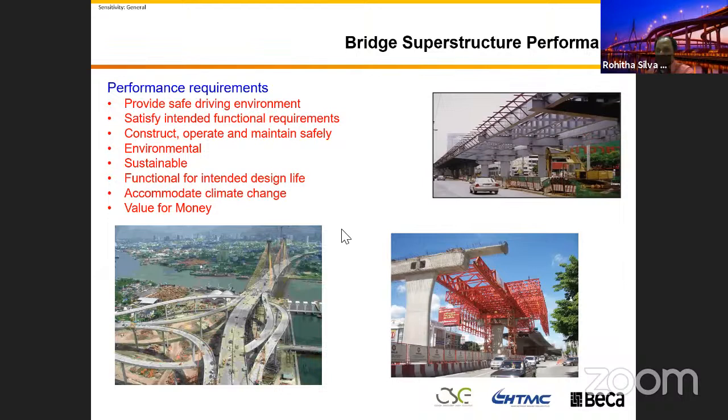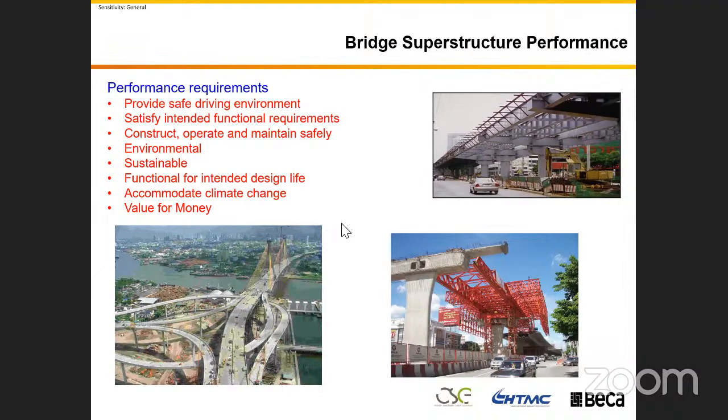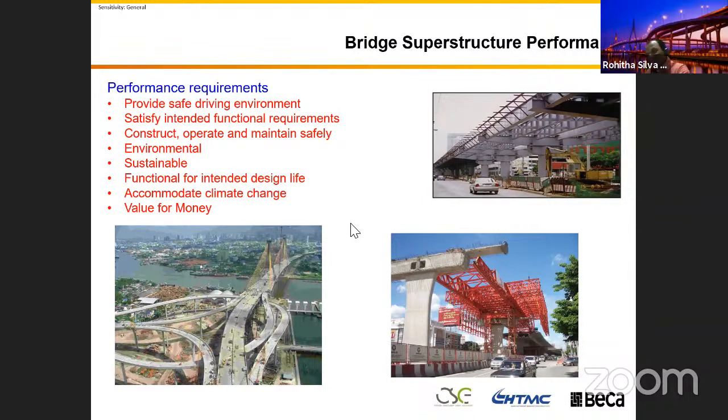Yeah. I think if you do have a thicker concrete element, then you would have to consider those effects. Yeah, of course. Now we do the analysis. If you are interested, I can send you the CIRIA recommendations. I have that one, even all the worksheets. You can do the analysis and see the temperature differential.